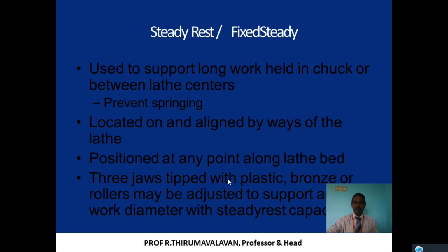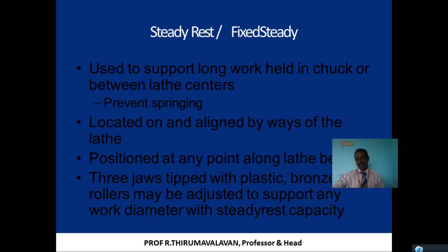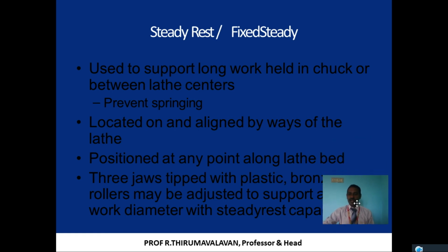The three jaws are tipped with plastic or bronze rollers, which may be adjusted to support the diameter. That is the steady rest capacity. But even with a steady rest, for longer workpieces it is rested at only one point, so there is a possibility of sagging. That can be avoided by using the follower rest.